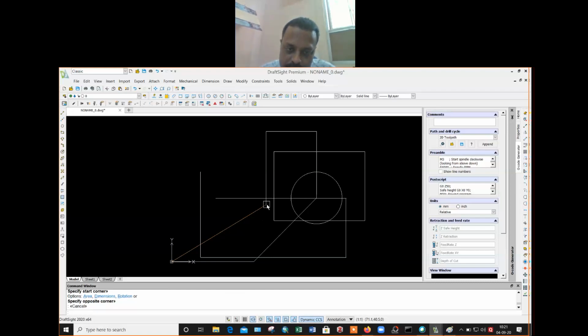I have deleted the line starting from this point to this point, which I shouldn't have done. Then in order to bring back that line, you'll have to undo many steps. One simple way to bring it back is type OOPS, oops. So oops will bring the, or oops will undo the,